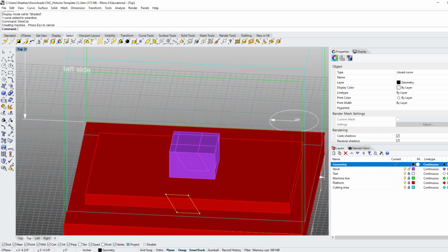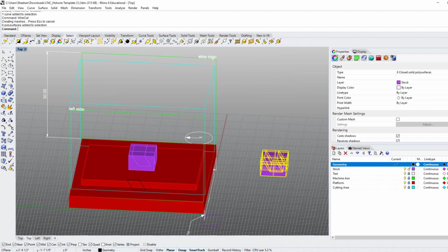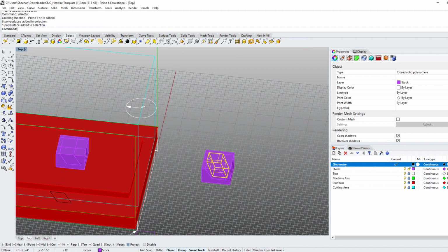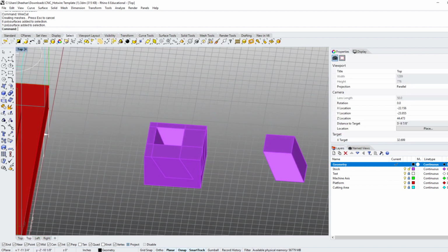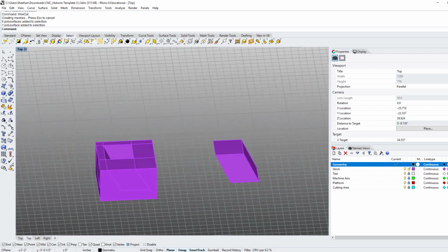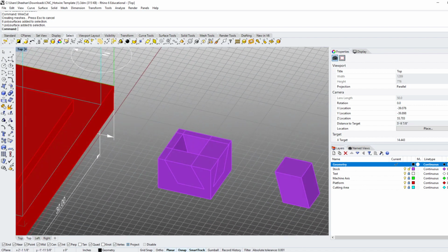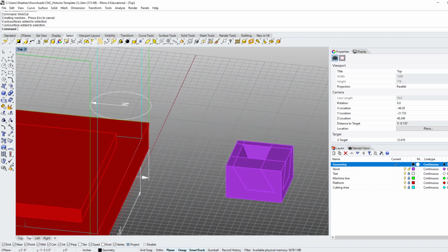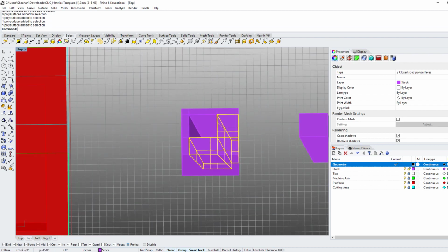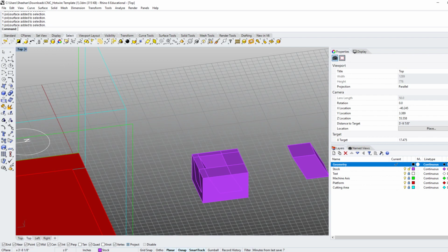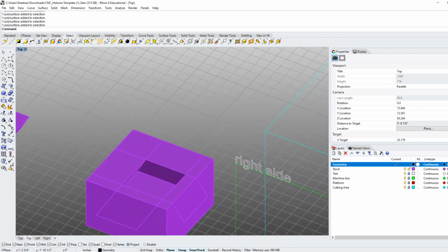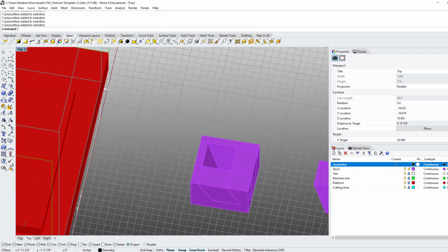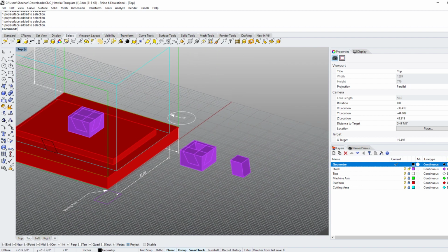Now I'm going to go ahead and pull this away so you can get an idea of what we've done here. So within that block is basically the three-dimensional intersection of this projection. So if I pull that guy out, you can see we have this kind of polyhedron, three-dimensional solid geometry. But because we cut it on the Hotwire, all the Hotwire really removes is a thin line where it actually melts the foam in order to cut through it. And therefore, we're also left with all the other parts of our geometry. And these parts that remain can be reassembled because we are also then left with a negative of that same volume. And we can use that negative, we can reassemble those parts to make a formwork to cast concrete into. So that's the basic operation.